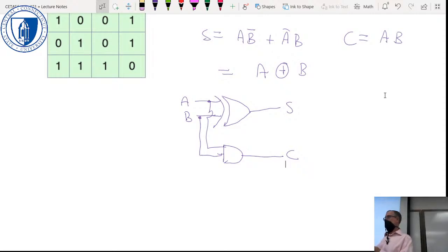I talked a little earlier about a mechanical switch and a pull-up resistor. You're going to have to use within Multisim a mechanical switch and a pull-up resistor on the input side of things in order to be able to show easily that you're changing the inputs.